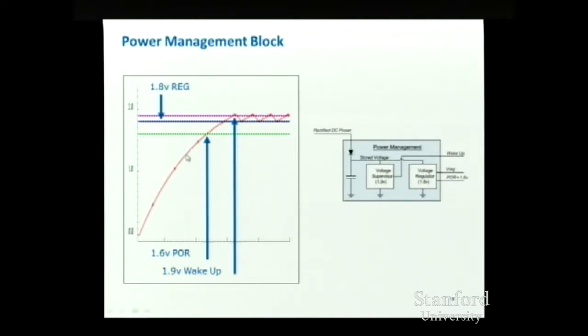So the microcontroller sleeps until this upper threshold has been exceeded. Once there's enough voltage, the microcontroller wakes up, does its sensing, does its communication. That causes it to spend energy, which decreases the available voltage, and it'll keep doing that until it gets to this lower threshold. When it hits that lower threshold, it goes to sleep and starts charging back up again, which is this upward trace.